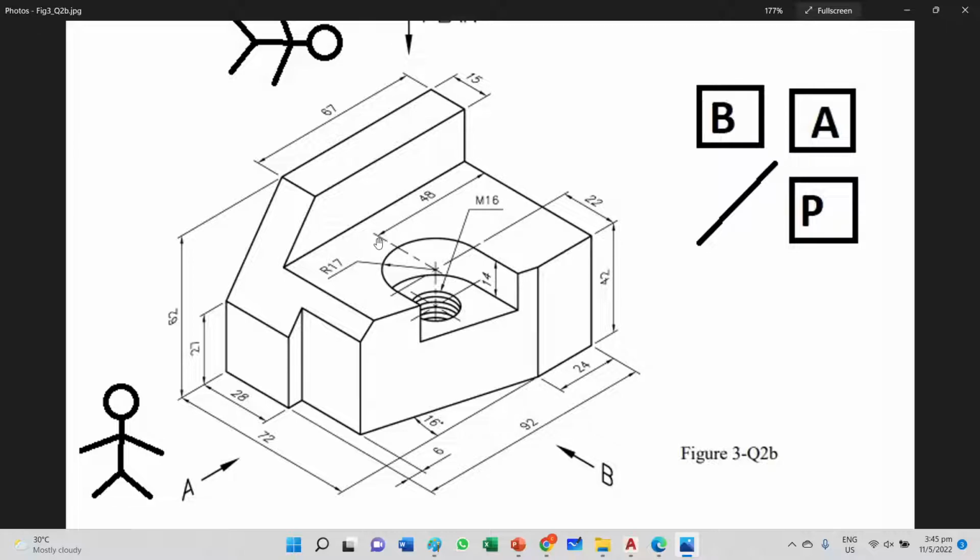So I'll probably start my 45-degree mitre line. I'll just put a distance of probably 200, not complete it because there are some unknown dimensions, and I'll leave it for later to do my projections. Okay, so I'll start with the plan view first. What I'll do is I'll clean up the drawing, selecting everything, that the height is 92, and the width is 72.